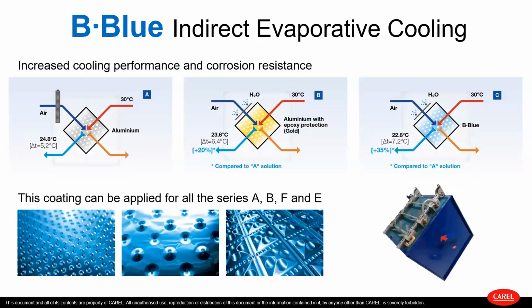As Luca anticipated, with the plate heat exchanger we can exploit evaporative cooling without increasing the humidity on the supply side, so in the outdoor airflow. We can do it in a different way with a wet pad, as anticipated. So we wet the air before the heat exchanger, then we go inside with the really cold return air with high relative humidity. But we can do better, because if we spray water directly on the heat exchanger, then we exploit this phenomenon more.